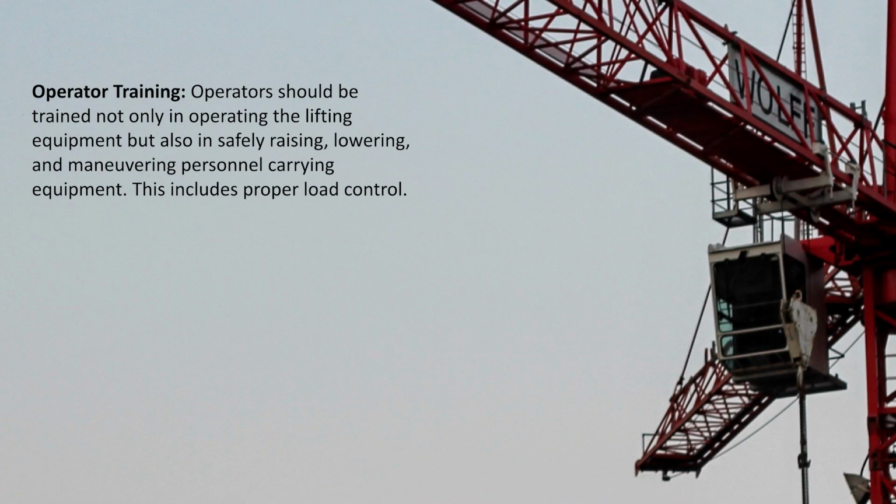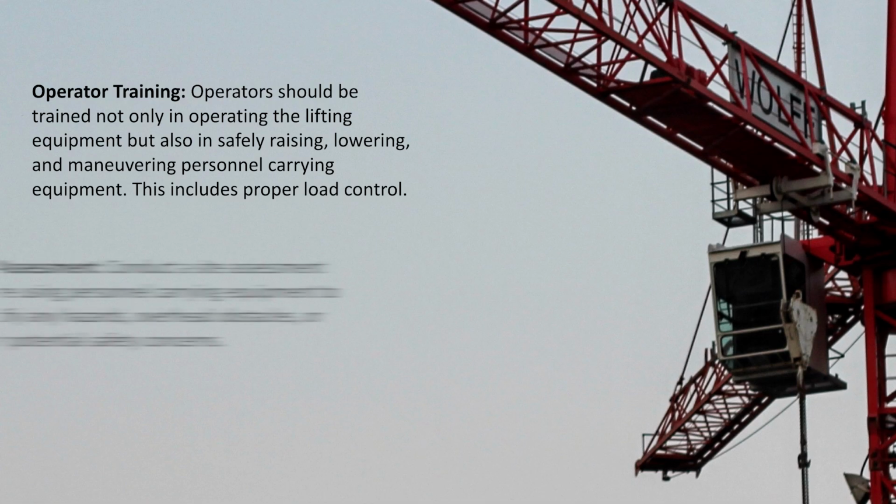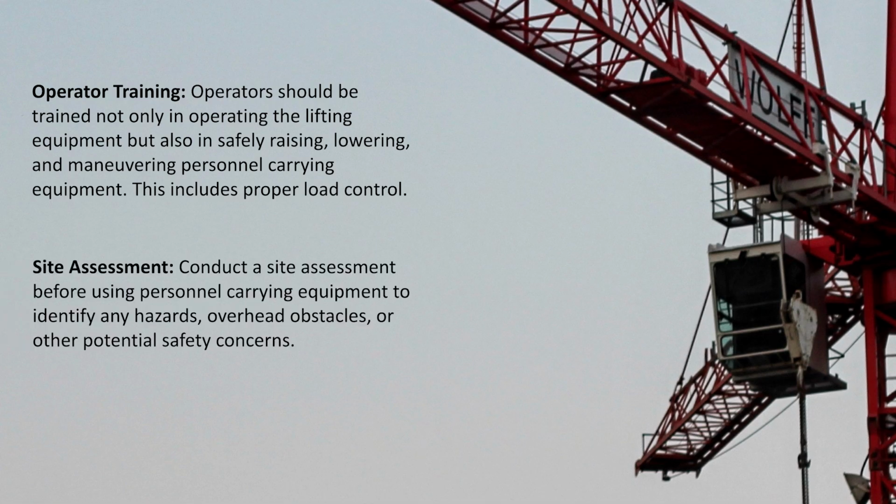Operator training. Operators should be trained not only in operating the lift equipment, but also in safely raising, lowering and maneuvering personal carrying equipment. This includes proper load control and site assessment before starting work at height. Conduct a site assessment before using personal carrying equipment to identify any hazards, overhead obstacles or other potential safety concerns.